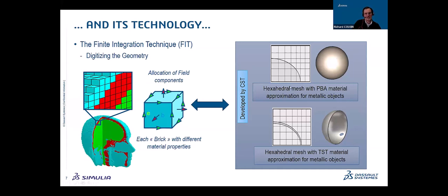And connecting this to the hexahedral mesh, compared to FDTD methods we don't have any staircase effect anymore. That means we really have an accuracy enhancement compared to FDTD, and with the number of mesh cells reduced, we can compute accurate simulations within reasonable simulation times.